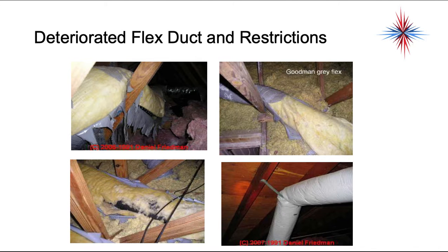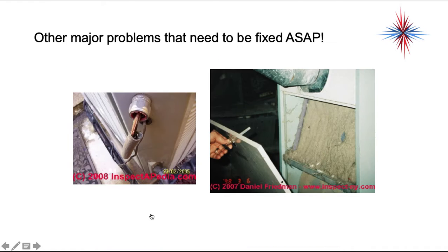Here's some problem scenarios. Okay, the one on the top left, you're missing a whole bunch of insulation. Not just the outer cover, but down here where my mouse pointer is right now, we're missing insulation. Here too. Here we have a duct being held up, it's coming down, so someone put a strap in, but it's a severely kinked duct. There's no way the air is flowing normally through that. Bottom left, again, more missing insulation, and the internal component is open.